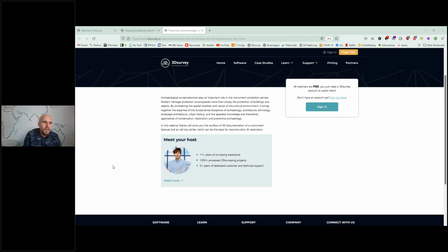Then the things you want to map with higher detail, record those from closer. If you are less interested in detail, you can also record from further away. But it will be hard to record things if you record at a 45-degree angle. You will be recording from, I don't know, maybe 2.5 meters away.